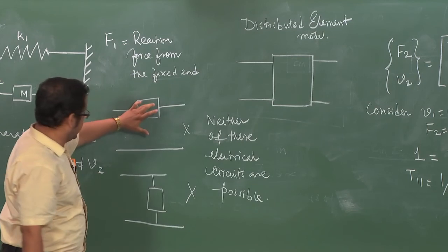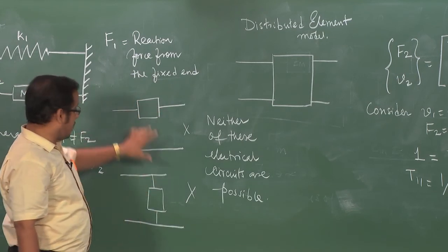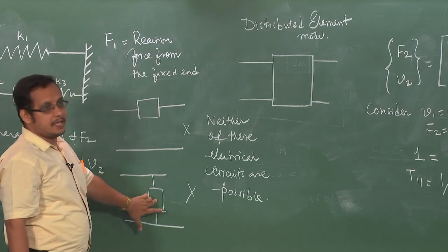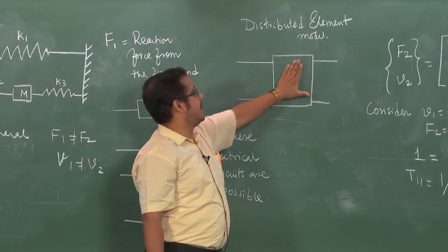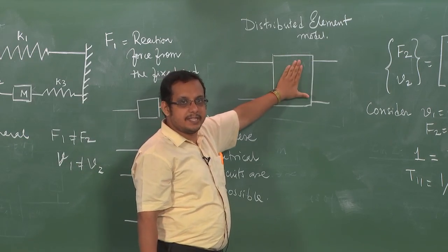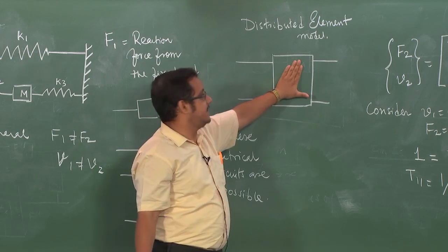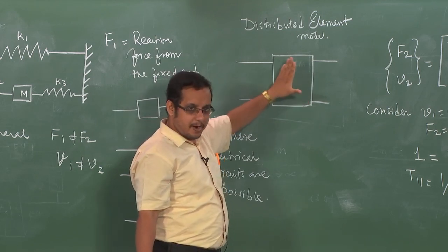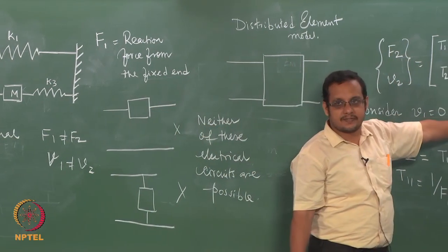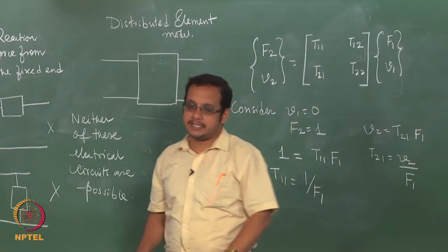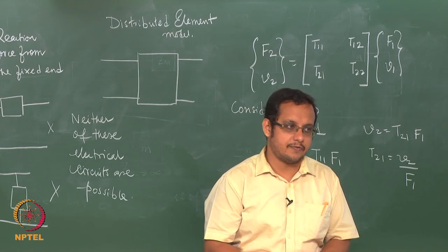You need not always think in terms of a lumped impedance or a lumped inline impedance or a lumped shunt impedance, but you could think in terms of transfer matrix. So, this element, whatever this electrical element is, I do not know what it is in realistic terms, but at least for the purpose of the analysis, this electrical element is that which corresponds to this transfer matrix, and we can implement it exactly in that same way through Simulink or other system simulation software.